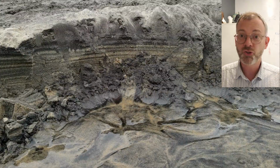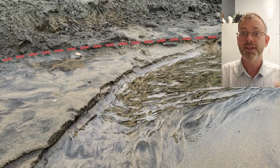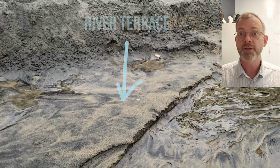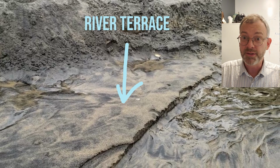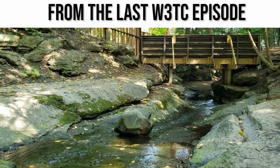In bigger storm events, there could be more water flowing through this channel. As you can see, it's much wider and the water's flowing in a narrower portion of the channel. We have different terraces. These are the flat areas on either side of the bank where the water isn't flowing. Now, if it floods, it may flow over into those terraced areas, but those terraces mark past flowing water levels